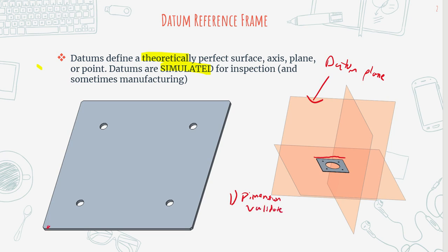As we talked about in our first video, you have imperfections in physical objects due to the machining process. You can just imagine how frustrating it would be if you were measuring off of edges on the surface itself, because your reference point is going to be shifted depending on the imperfection that you're measuring from. It just makes everything really confusing. So the way that they do it instead is they define a datum, something like a datum plane, and they measure off of the datum plane instead.